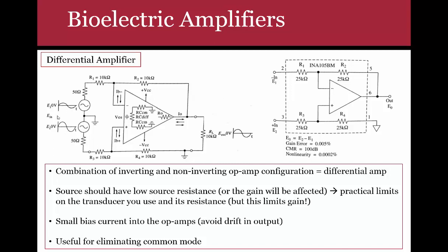If they both have the same voltage offset, which in this case they will because they're on the same human, then you can use a difference amplifier to subtract the difference between those 2 electrodes. What ends up happening is that you subtract off the common DC offset that is on both of them. So this is just one way to get rid of that extra offset.